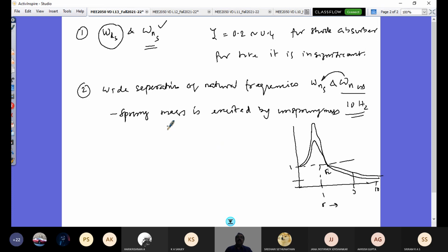So your suspension system and unsprung mass act as a good isolator for your vehicle, and any excitation that comes at higher frequencies due to road interaction would be nicely isolated. Your sprung mass will have a very small amplitude of vibration, or almost none. That does not mean you will not get low-frequency vibration energy inside the vehicle.